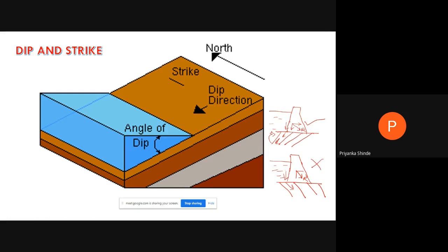So this is not safe and this is safe. Here the resultant R is parallel to the bedding plane, so there are chances of sliding of the dam because of this resultant force. This is one example in the case of a dam.